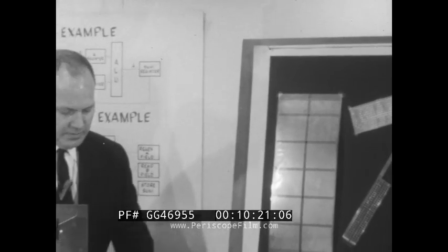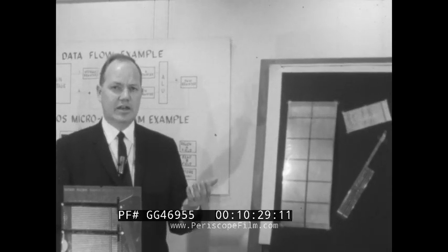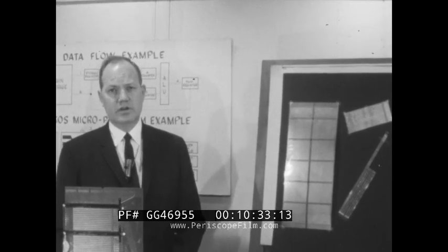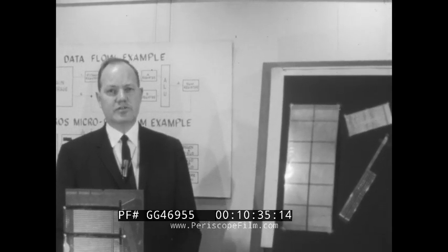All right, from the read-only storage control then, I would like to simply go through a very simple example of add A to B and store the result in C with a representative data flow and a representative example of microprogrammed instruction. It's very basic, but I think it will help give you a better understanding of read-only storage.